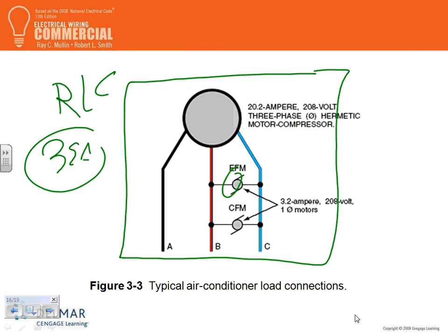The HVAC guy on a commercial job is going to be installing the control switches for it. All this info comes pulled to a controller that comes with the equipment. The HVAC guys really don't even wire it internally. They bring the external control class 2 circuits and they tie it into terminals provided in the controller.